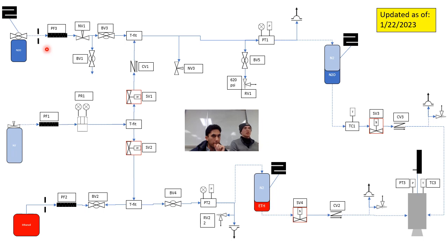there's a case where the nitrous oxide bottle does depressurize pretty quickly, which means you have a small nitrous oxide bottle, and then the pressures equalize between the two systems, which means the liquid flow no longer moves this way. Then you need to follow the disconnect steps, which I'll talk about in a second.